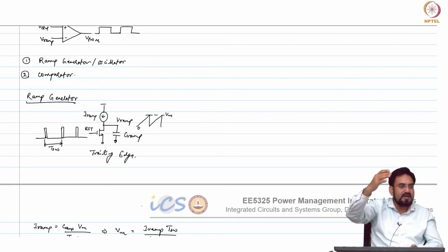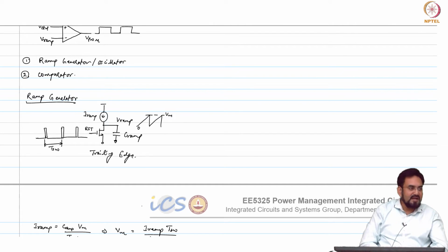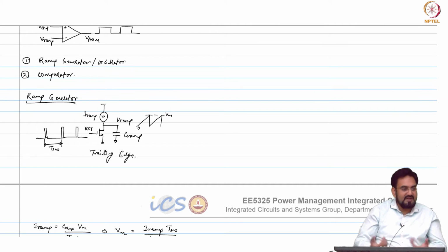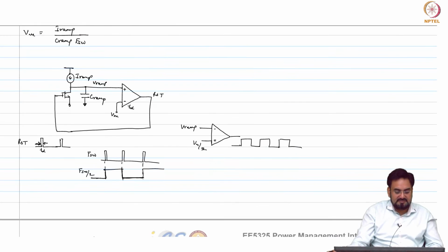So still you will have a 0.8 volt headroom. And I know I will never hit the lower voltage, because my operating duty cycle is not going below 50% or so. So the output stage of your amplifier will always be in saturation. So that is one way, but if you are operating at the entire range of duty cycle, then you have to shift the common mode, you do not have any other options. So you have to decide based on what your specifications are.